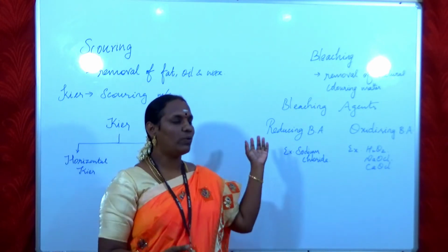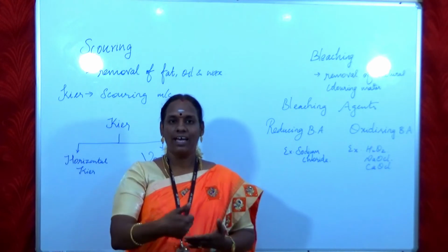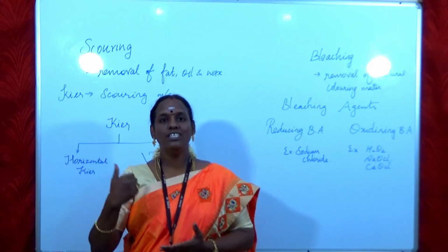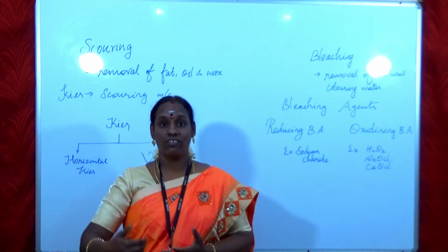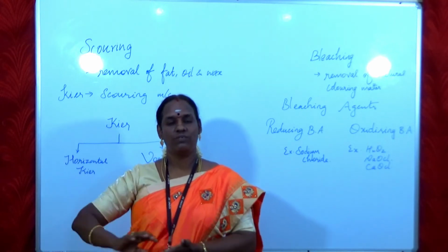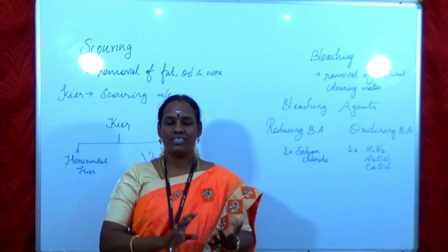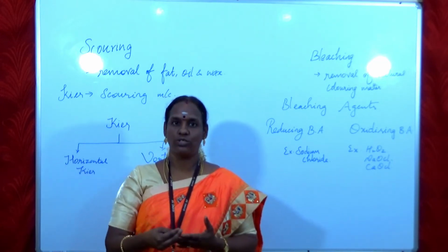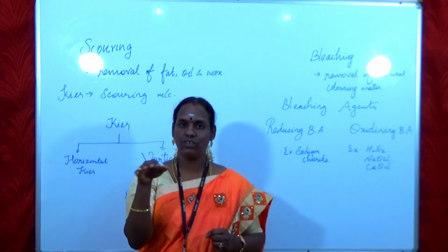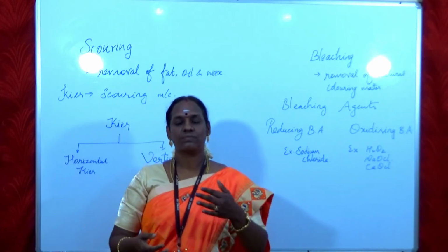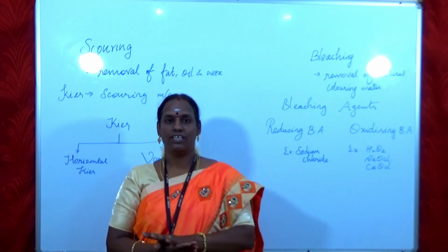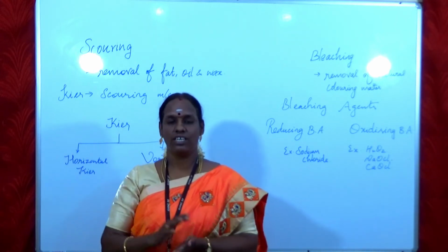The insoluble oil and wax react with the soap, and this process is known as emulsification. Because of this process, the insoluble oil, wax and fat are converted into a soluble emulsifier. So the soluble solutions can also be removed in the washing process. The pectins and some other matters are also converted into soluble matters. Any minute solid particles present in the fabric are deposited in the liquor, so they can be removed through the filtering process.